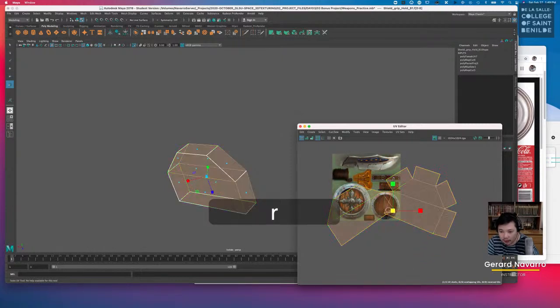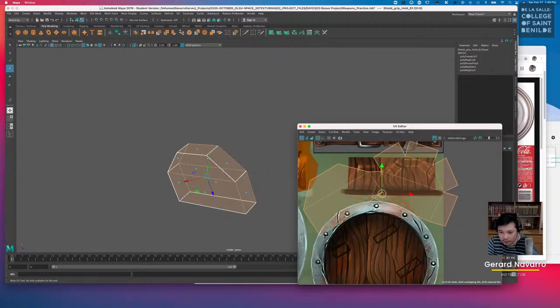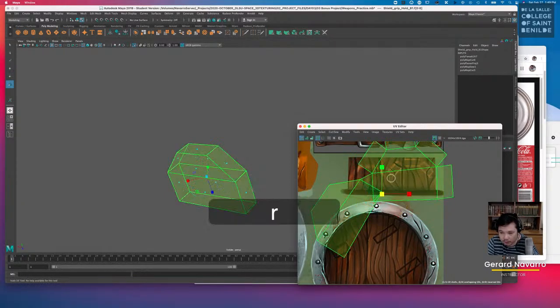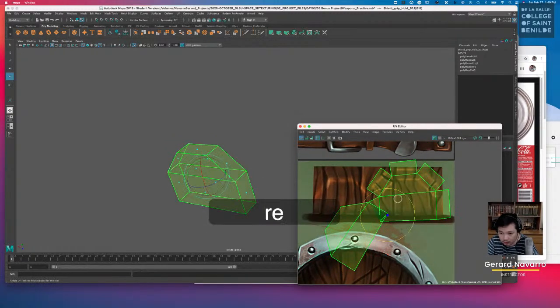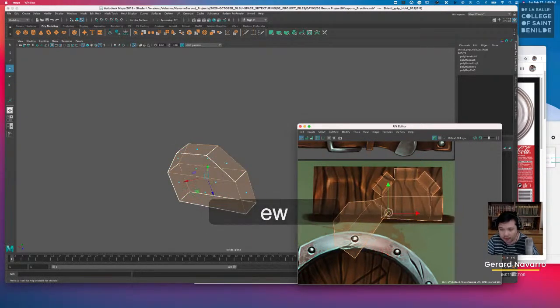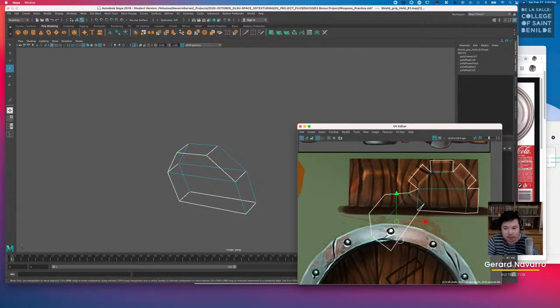So, ang gagawin na lang natin is select our UV shell, rotate it like so, and then itapat natin doon. So, medyo hindi malinis ang pagka-rotate niya, pero we can do this manually naman with selecting the UVs. So, I'll show you how. So, siguro itong isa, ipapantay ko na. So, ipapantay ko na siya like so. So, ayan. Papantay ko na siyang ganyan. And then, I'm going to select the rest of the UVs over here. And then, let's rotate them together. So, i-rotate ko siya.